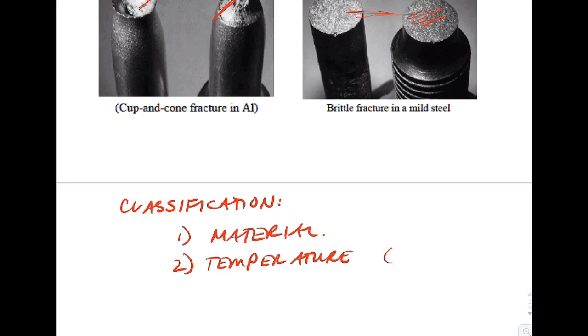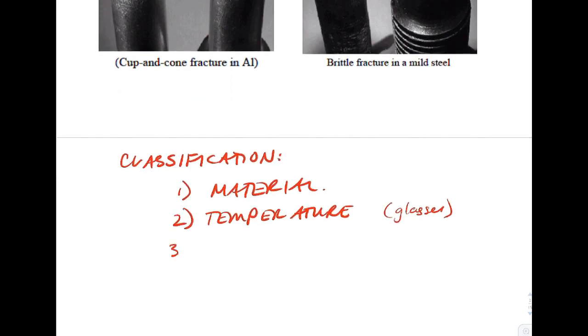The most common example you might think of is glass. When heated up, it goes from something very brittle to something extremely ductile at high temperature. It's not just a material issue, but also the rate of loading. Something that is loaded slowly may act in a ductile nature, as opposed to something hit with an impactful load, which may respond in a brittle fashion.